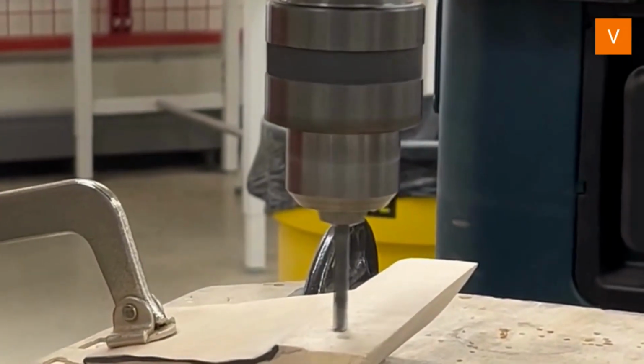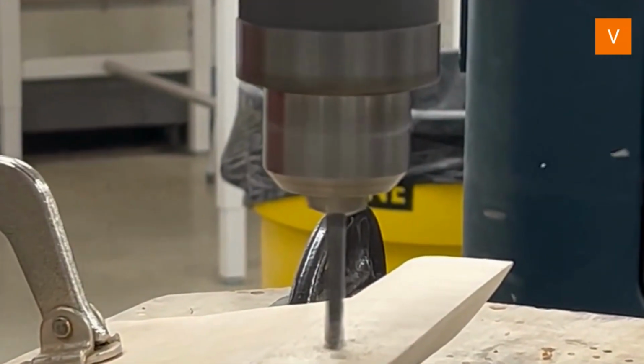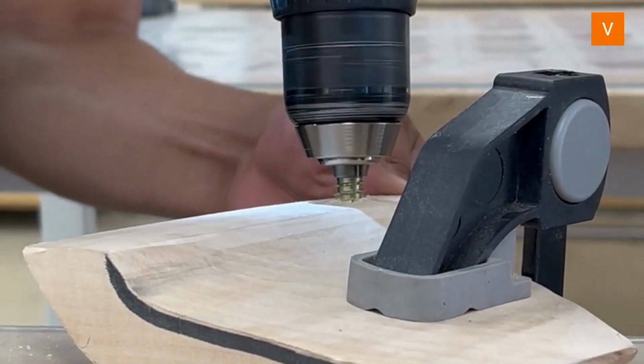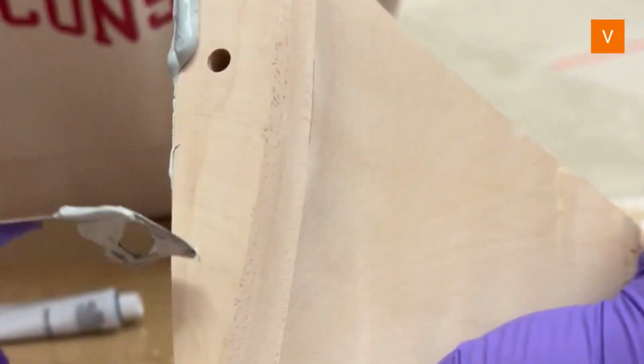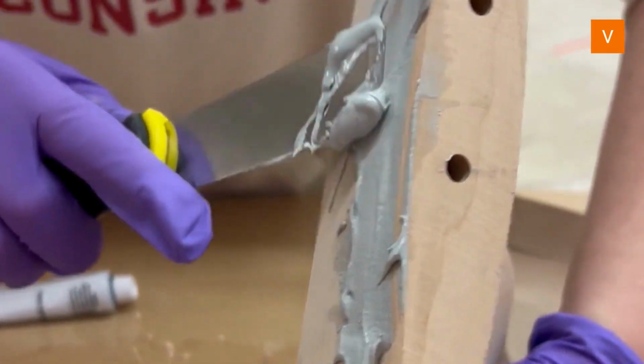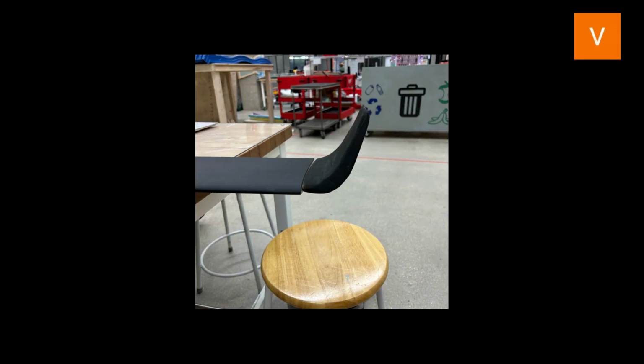Then we drilled holes into the winglet using a drill press for screws to go through. We then installed threaded wood inserts into the wing using a power drill. The wingtip piece and attachment piece were attached using wood glue and Bondo adhesive. Finally, we applied a smooth finishing coat of Gorilla Glue waterproof sealant on the winglet to complete the fabrication process.